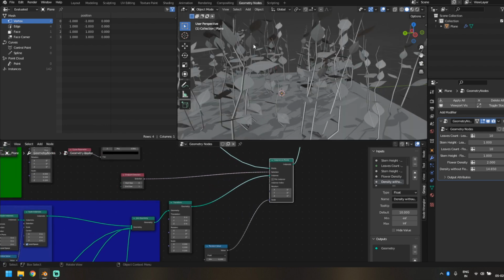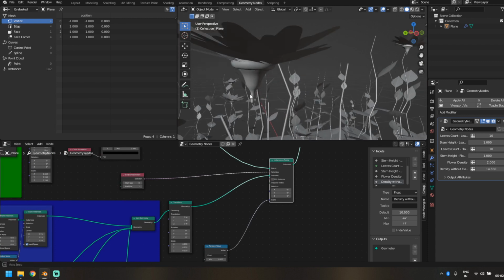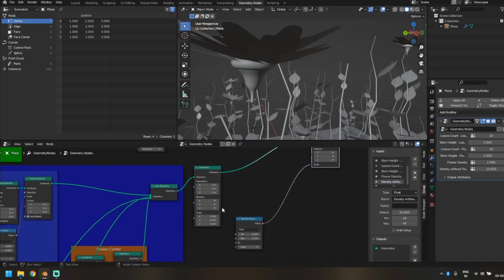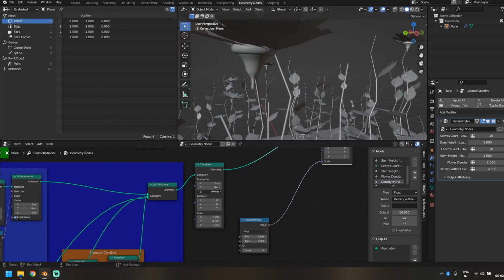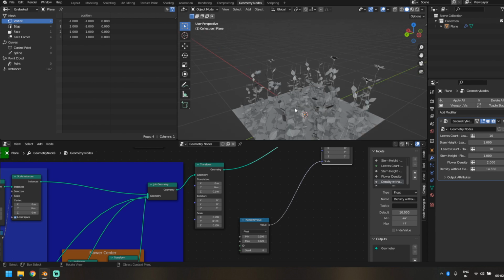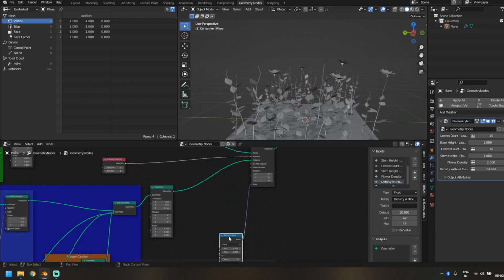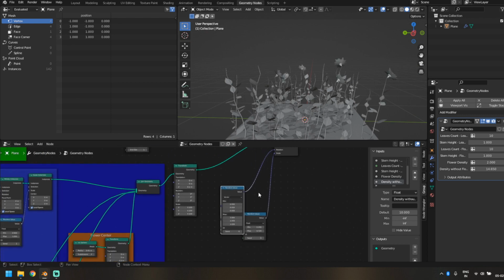Also for the flowers, if we look closely, it's not directly over the stem. It's just floating somewhere around it. So let's bring this up using this transform node so that it's sticking right onto the point up there and doesn't look odd. And for the rotation, I'm going to do a Shift D, change it to vector, and add this here.